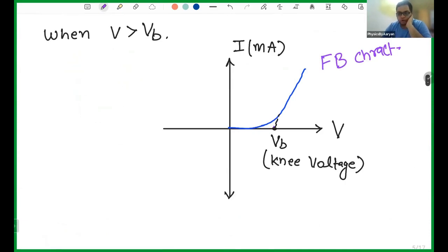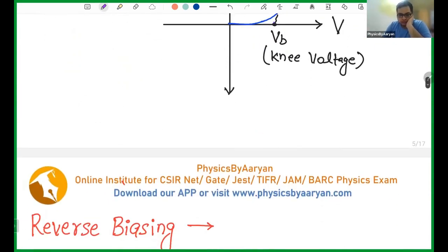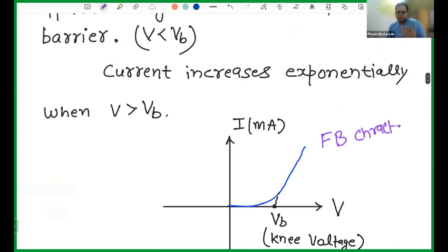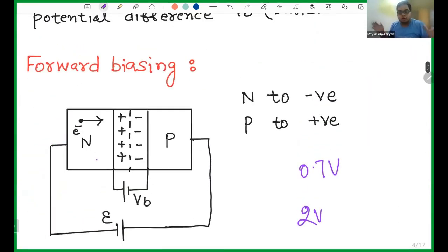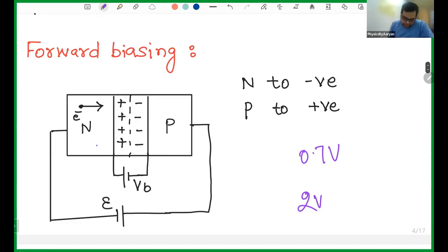Okay. Now let's come to the reverse bias. Before the knee voltage, is the current due to minority charge carriers? So how can minority charge carriers flow? We have to apply the negative voltage for that. So let's say current because of minority charge in forward bias. Now N has holes as well, and P has some minority electrons. Even if these electrons want to go in this direction, this positive battery will not let them go, because this positive battery will attract these electrons towards it. So this positive battery cannot allow the electrons to move in this direction.